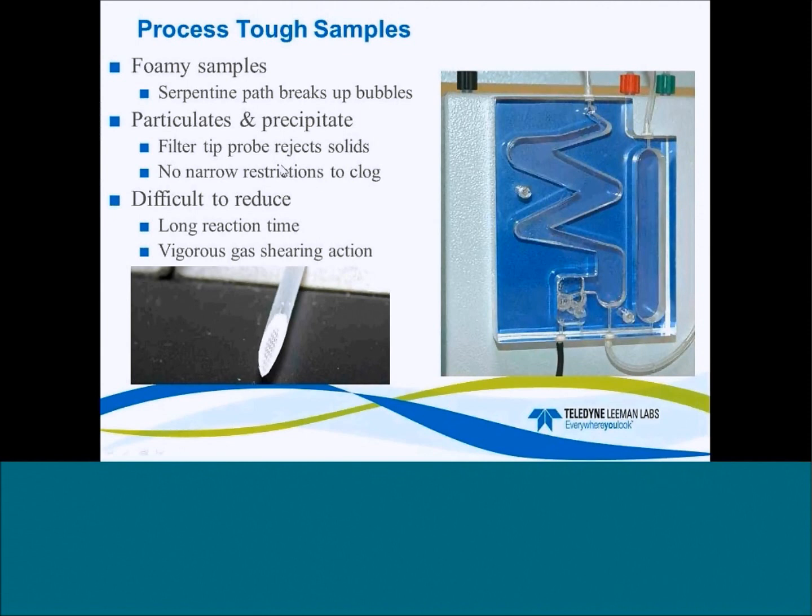Secondarily, there are problems where you may have a precipitate at the bottom of your digestate, and that can clog orifices that may be located throughout the rest of the system. And what we do with our sample probe is we actually attach a very fine Teflon mesh to the end of the sipper probe so that it occludes any of the particulates that could end up getting into other systems and clogging it.